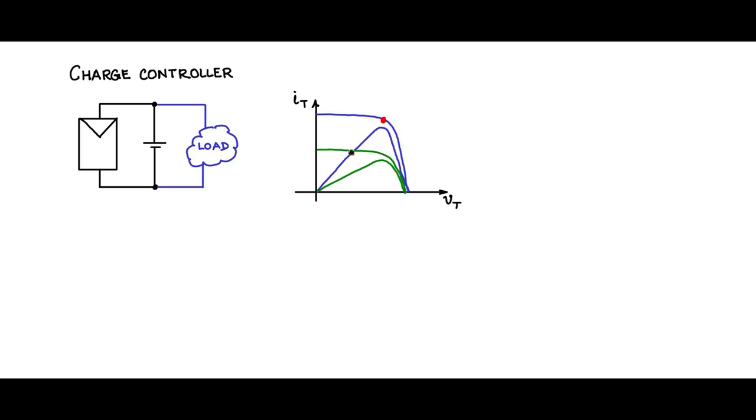So I have this changed IV curve for the new insolation and the PV curve, and the optimal desired operating point would be somewhere corresponding here. So let me mark that point. Now it's still for the different insolation, I have an operating point like this.